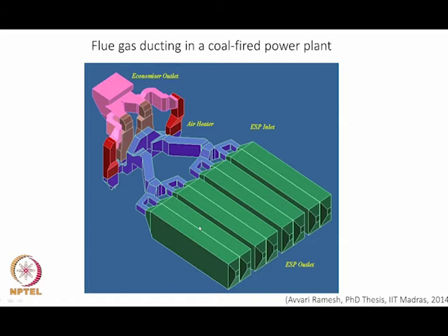So, in practical problems you cannot honor the kind of L/D ratios that are usually required for a specific correlation to work, or for some analysis assumptions like fully developed flow to become applicable. So, you need to deal with the practical compulsions, and so you would say you take a rapid close bend here, and from here it has to split into 2. How do you split it into 2? Analytically, very difficult. It is very difficult to predict what would force the fluid which is coming from this and going through a sharp bend like this, to split evenly between these 2.